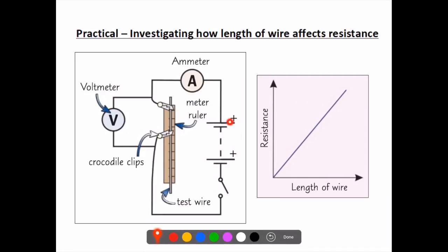Okay, so this is our setup. So here we have an electric energy supply. You can either use a battery or even a single cell, but again, make sure you know the orientation. This is a switch, and we need to use the switch to kind of change the length of the wire. So we have to turn it off when we're touching it. As you can see, the wire is continuously going like this. However, now we have crocodile clips, and then the electrons go from here into this wire and then back out. So here's your complete circuit like this.